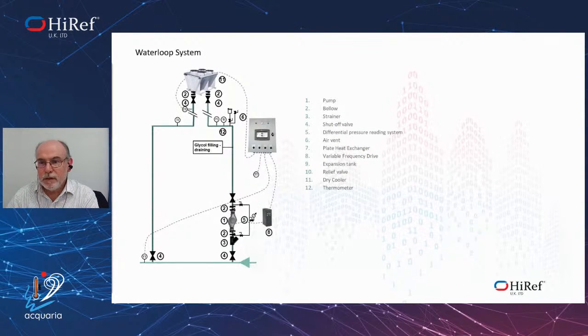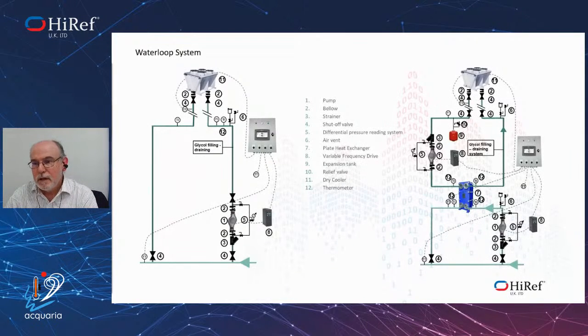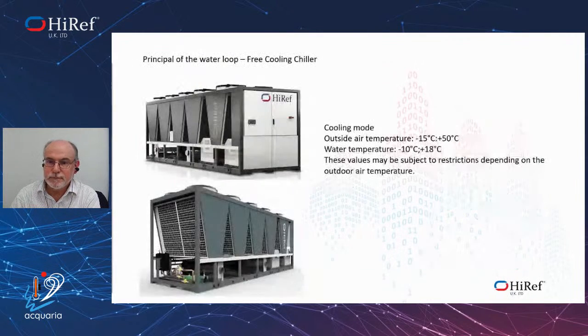And so if you look at a Tricooler, you would either go direct through, so you can't put glycol in unless you're putting it through the whole system, which is then making a problem, or you decouple it through a plate heat exchanger, and then end up with a variation in temperature between outdoor and indoor loops. So your primary and secondary, there's a differential of around 3 degrees.